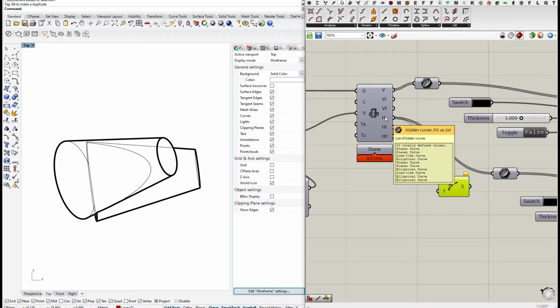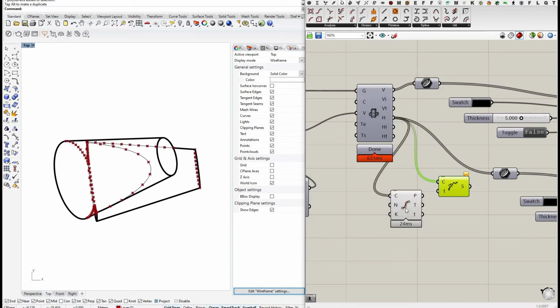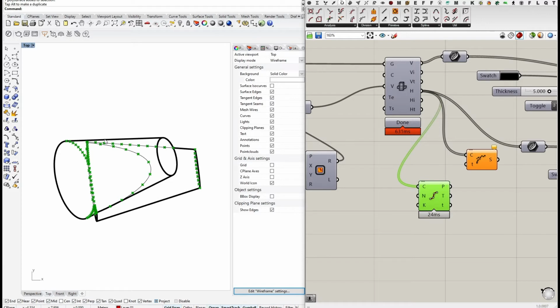And because our curves have different lengths, we can do this either by the actual length, or we can do this for each curve individually as a kind of fixed element. So for instance, we can use the divide curve component to generate, let's say, 10 divisions. In that sense, we would get dashed lines that sometimes are very dense and sometimes have very large dashes.